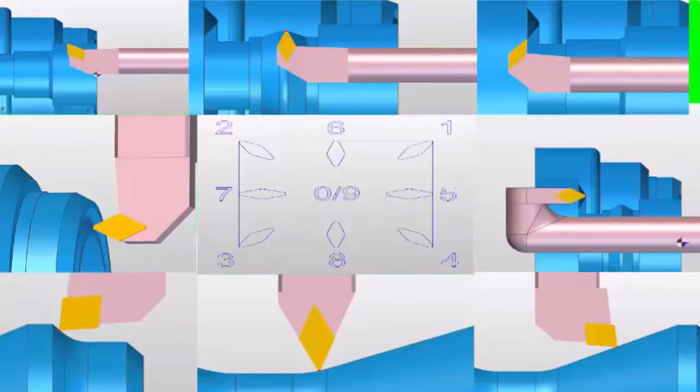The thing to remember is with these tools, with the neutral type tools, like this one here for example, you've got to take the Z figure from the center of the tool. It's not one edge, so it can be quite tricky to check these and to set these up, and the same with these, the face grooving tools. So that's something to remember there.